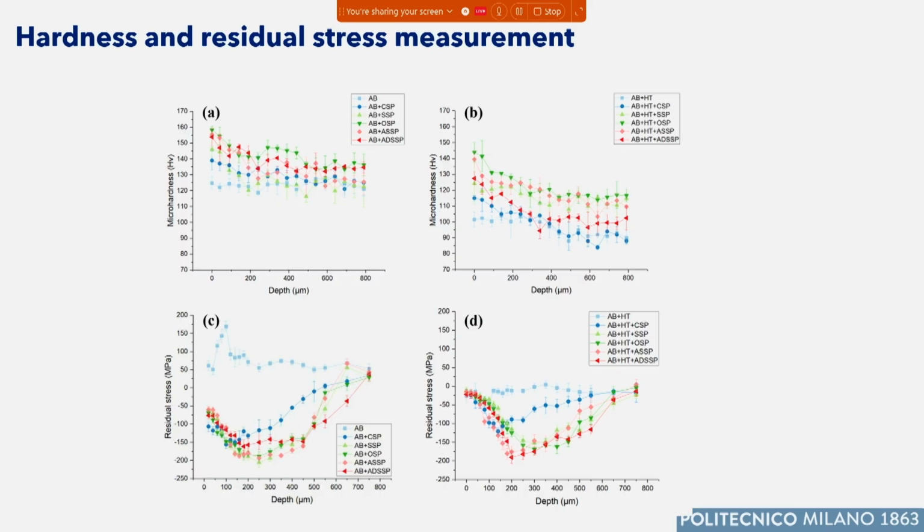Here. Okay, so CSP is this. And you are comparing with gradient shot peening, that is the green and gray that are here. So the surface residual stress is different, but not very different. What is more, the curves are diverging, and the gradient shot peening is going deeper.